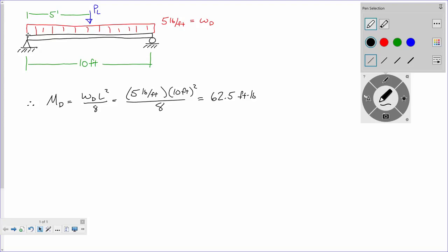Yep. Okay, now let's see if you all can tell me what the expression for the live load moment is going to be. P_L L over 4. And you get that if I look at the shear diagram: it goes up P over 2, and that distance is L over 2, so the area is P over 2 times L over 2, PL over 4. Y'all remember that?